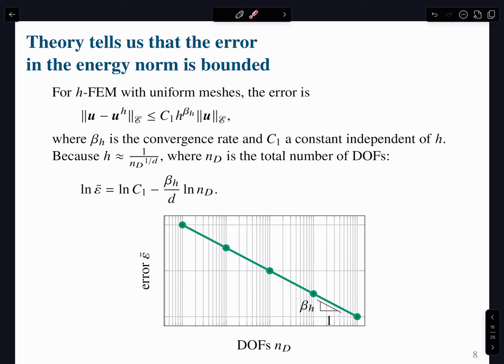They have to be always defined on fine meshes, and on fine meshes, the number of degrees of freedom that are tied to the boundary is just a very small fraction, because again, it's a lower dimensional manifold, right? Like a curve in 2D, for instance, right? If you account for the number of degrees of freedom, as you reduce the mesh size, that is going to be just an increasingly smaller fraction of the total number of degrees of freedom.